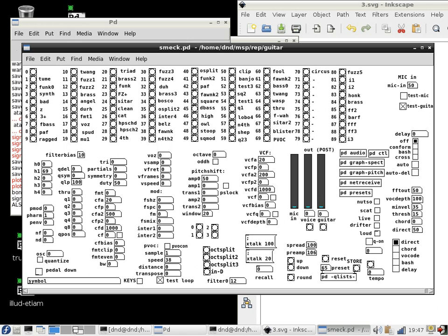But on a guitar, since there are 6 strings, you better get the strings separately so that you can pitch track them and so that you can apply a separate comb filter tuned to the pitch of each string. Otherwise it won't work.